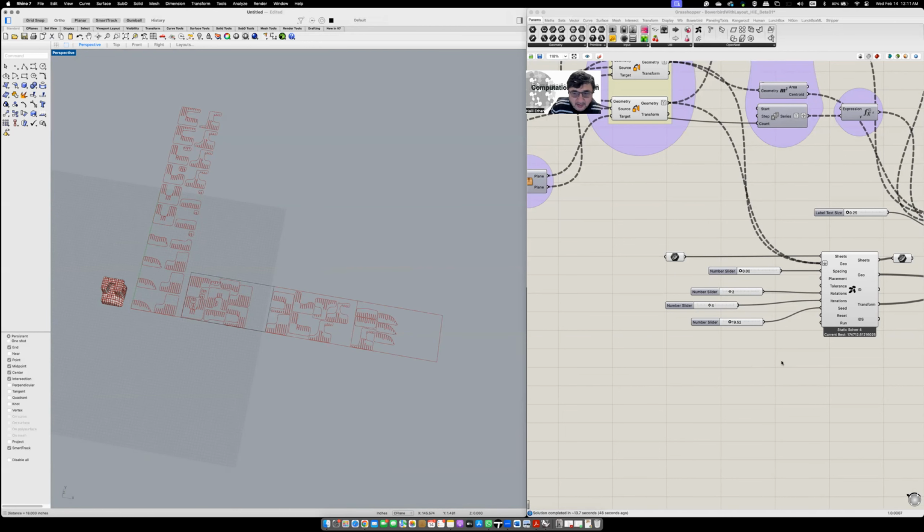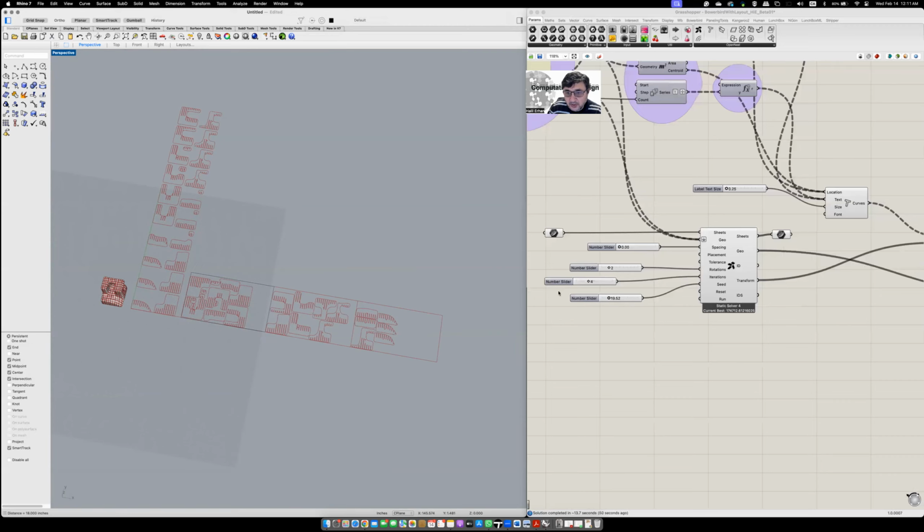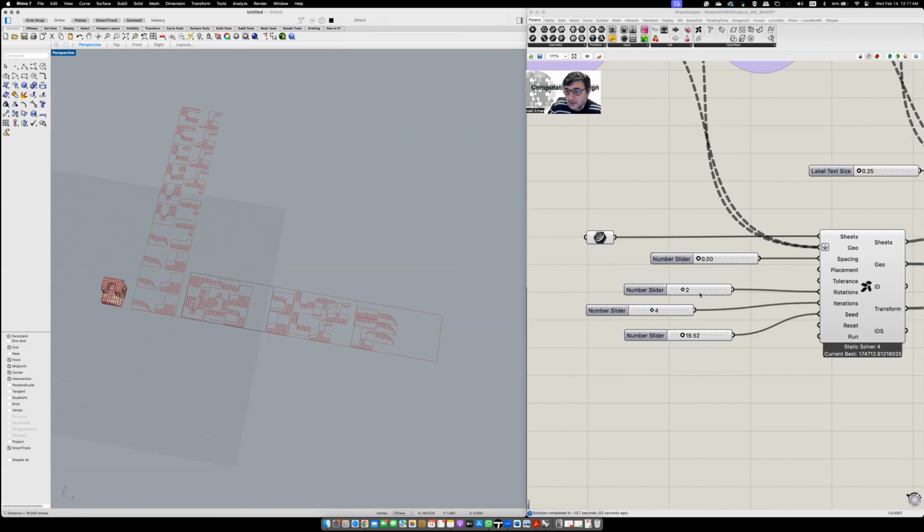Mine is bulky. But if you come here and look at the spacing, it is almost 0, right? So for the spacing between the slices, let's give them a little bit of room so that laser cutting doesn't overlap. Maybe a quarter inch, maybe 1/10 of an inch.